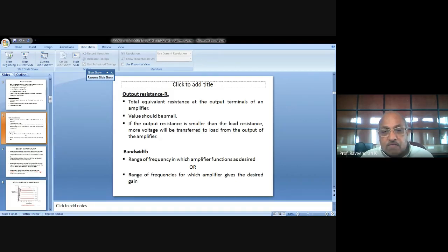If IC is the current flowing through the resistor, then the voltage drop ICRC subtracted from VCC gives the output voltage here, if you apply Kirchhoff's voltage law on the circuit. So these are all simplified with KVL and KCL, and the design is simplified. That is how the output voltage varies.